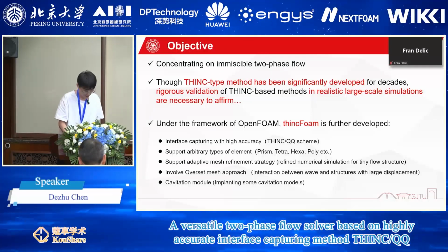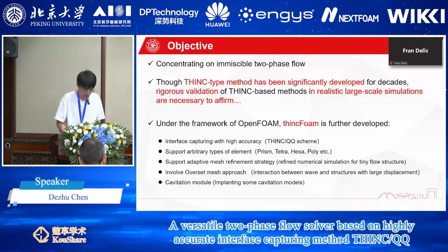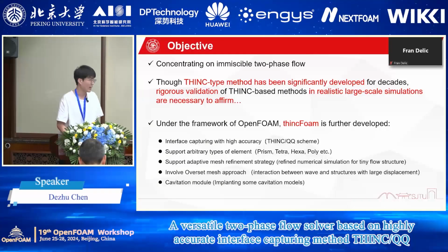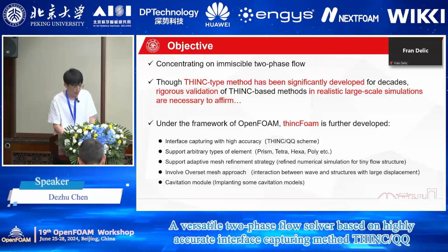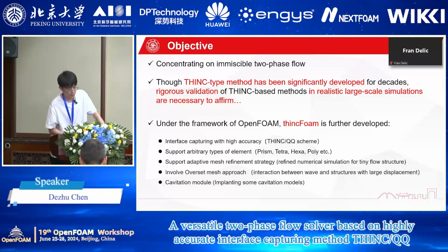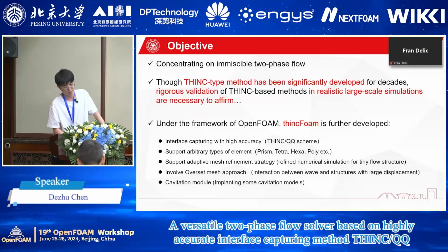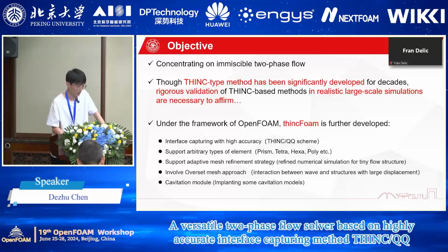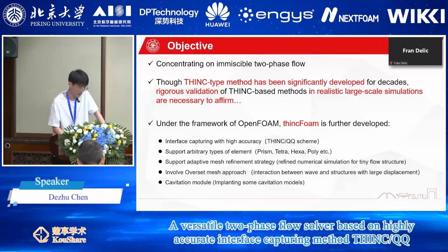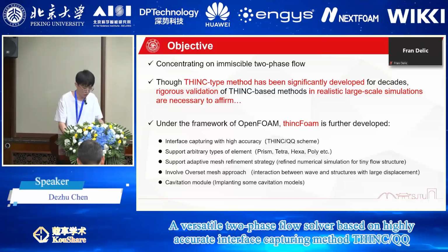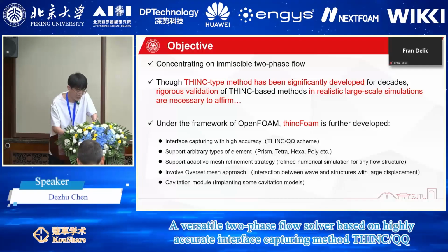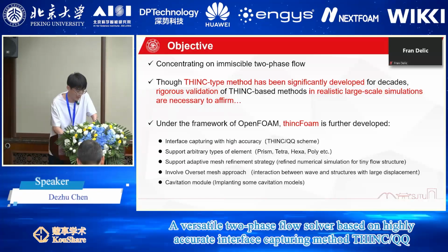As well, it supports adaptive mesh refinement strategy to conduct refined numerical simulation for tiny flow structure, and to handle the strong interaction between wave and the structure with large displacement, we use overset mesh approach. And also we implemented some cavitation models to simulate the cavitation flow.